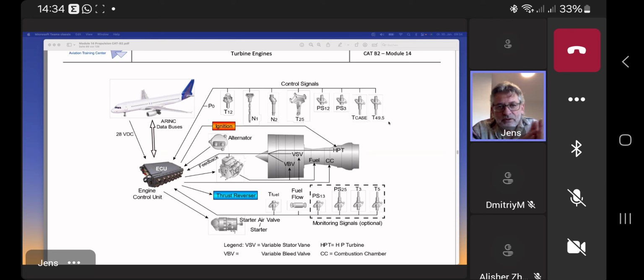Yeah, the older the engine gets, the higher the EGT will be. And this is a normal reason also for replacement. All engines will reach their limit with the EGT. You will probably also remember the name EGT margin. The difference between the real measured EGT and the maximum allowance.